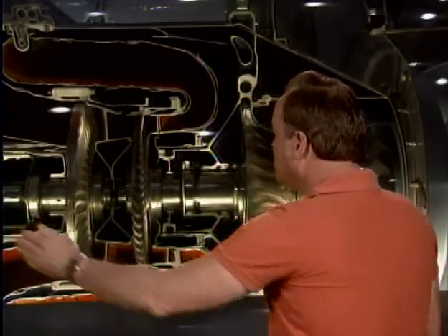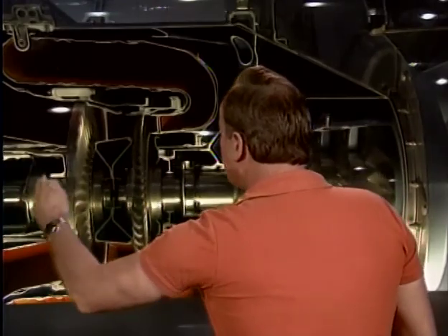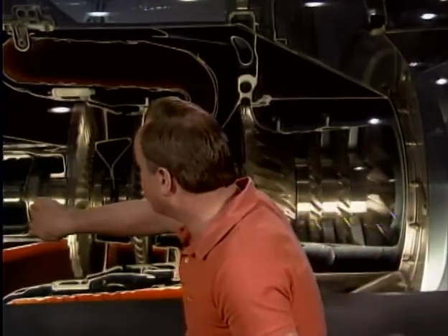All right, there's also a turbine discharge pressure indicator sensor on a turbine engine, and that's normally on a pure jet engine. At the aft part of a pure jet engine, you have a pressure sensor back there, and it's located immediately aft of the last turbine stage. So where would the pressure sensor be for instance, EPR, the aft one? Immediately after the last turbine stage.